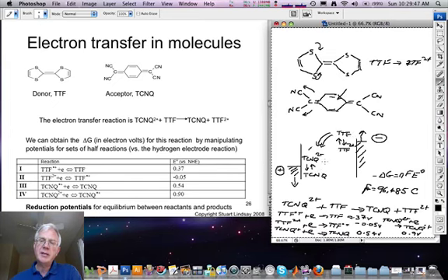Conversely, the TCNQ will readily donate electrons to this electrode if its bias is positive enough, i.e. this Fermi level lies below the level needed to accept electrons from it, and so it will then start off in the TCNQ2+ mode. It will readily accept 2 electrons from the TTF, and that will then make it neutral TCNQ, but because of the very high positive bias on this electrode here, this will instantly cycle back to TCNQ2+.